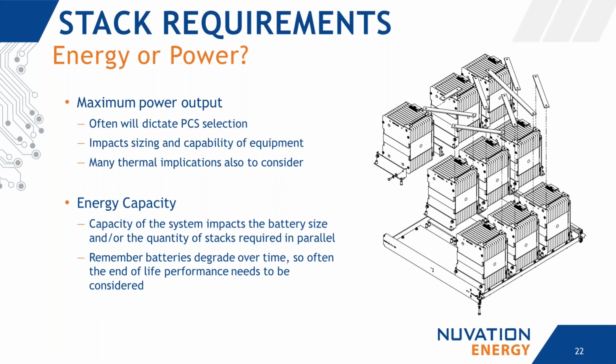Understanding the energy requirements determines the capacity of the system, which in turn impacts the battery size and/or the quantity of stacks required in parallel. And it's really important to remember that batteries degrade over time. So often the end-of-life performance is what needs to be considered when sizing the system.